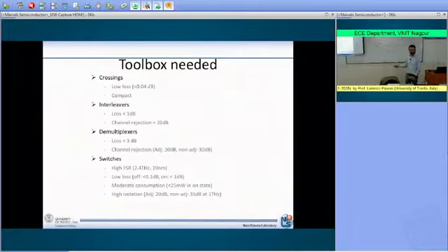The switches are the microring resonators. And here you see the free spectral range. So the separation between the different resonances should be larger than 2.4 terahertz. Why so spaced? The reason is that we have a comb of frequency, a comb of wavelength, and we want this comb of wavelength to be allocated within a single free spectral range. And so this means that the two resonances of a ring should be separated by this quantity.